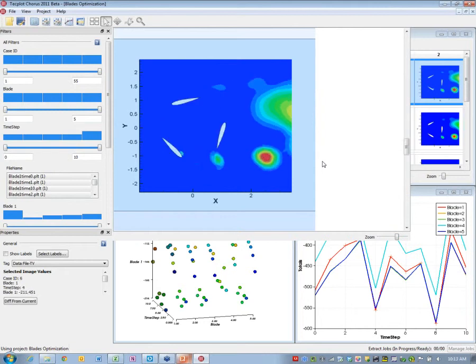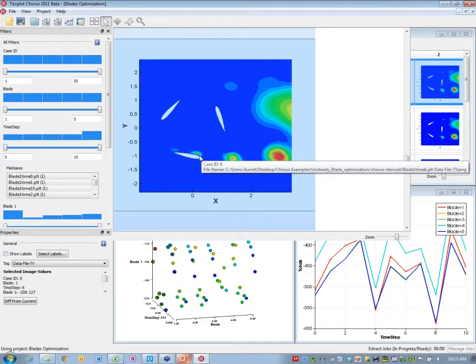One thing to point out as I walk through here is the vortex shedding. The authors were trying to optimize, and this is a use case that was courtesy of the folks at Pointwise. We did a webinar on this very case where they were trying to maximize lift on these blades. Here's a good example: in this area you're starting to see a formation of vortices on the leading edge, and that's decreasing the performance. You want to avoid the large scale separation as much as possible.